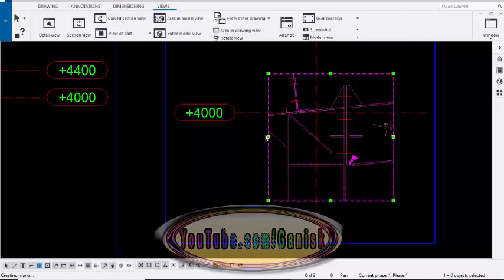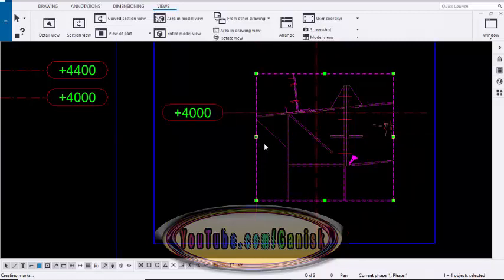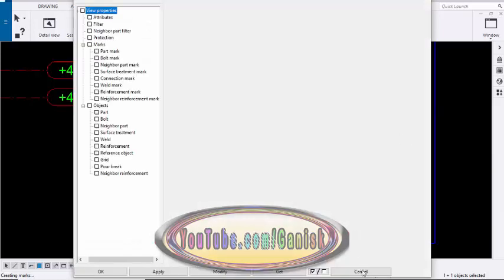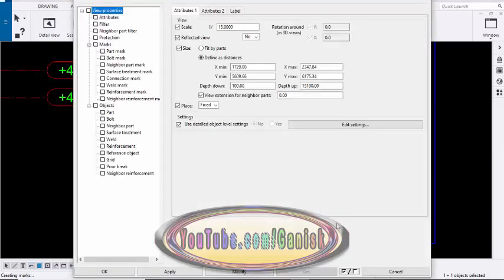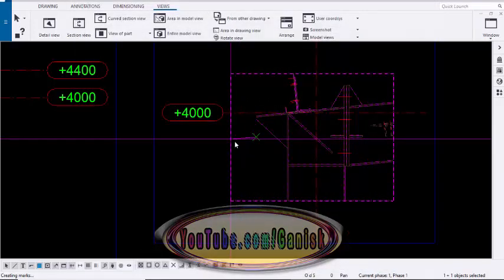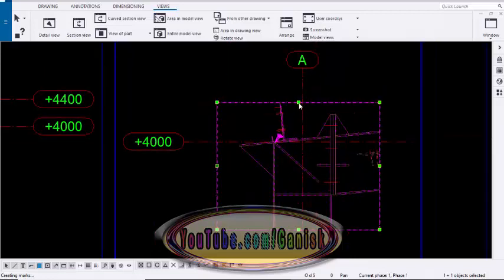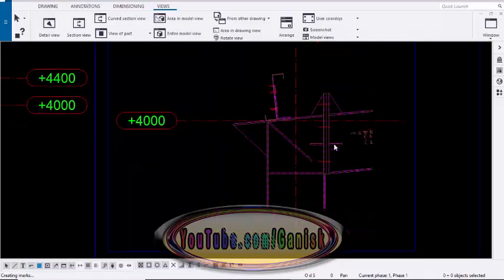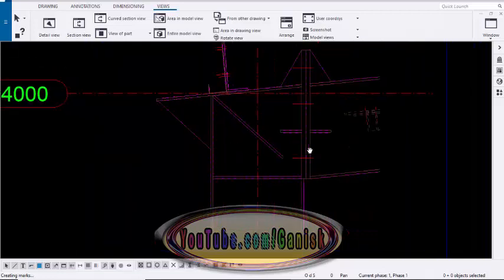So click on here and you can adjust this display a little bit larger. You can increase the visibility depth also. Click on cancel here and don't double click on this border, just click once and you can drag it to increase the visibility depth like this. Okay, now we're going to give the connection details here.